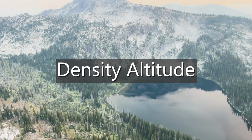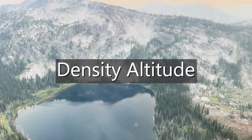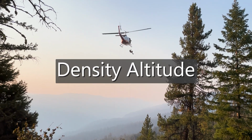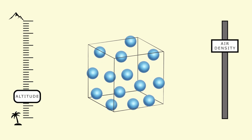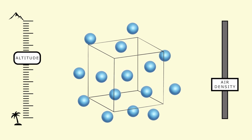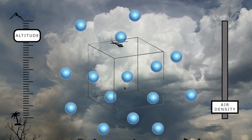Density altitude. By definition, density altitude is pressure altitude, or elevation, corrected for temperature and humidity. It can have a profound effect on aircraft performance. Air is said to be thin at higher elevations. There are fewer air molecules per cubic foot at 10,000 feet than at sea level. As altitude increases, air density decreases. Lower atmospheric pressure allows air molecules to move farther apart.